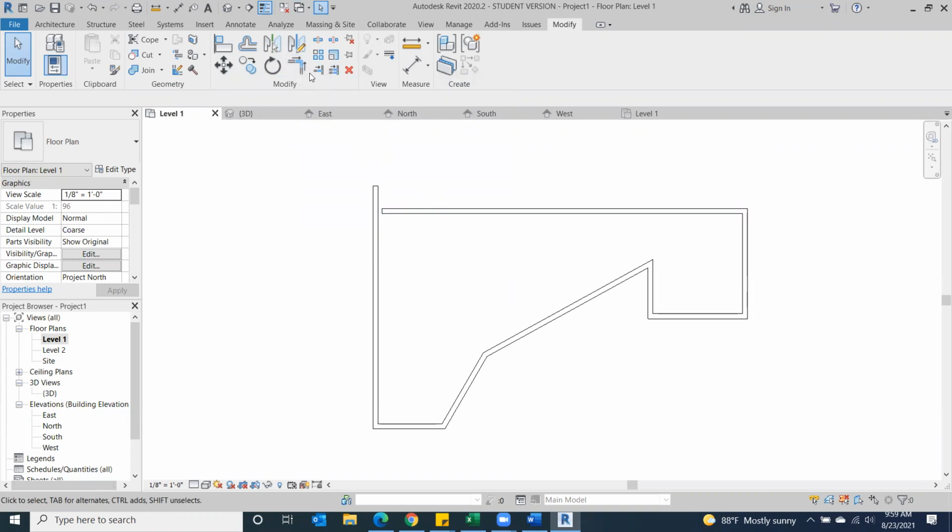So if I wanted to close off this end right here, I can click my Modify corner tool. I'm going to click on the internal angles of what I want. So I want this to end at this point. So I'm going to click on this internal angle. And I click here and I click here, and it's just going to cut that off like that, which is nice. Now, let me go to undo. And say if I wanted to make it connect to this wall and this wall, and wanted to get rid of this one, then I would connect these two angles right here. Those two internal angles, and then it'll cut off that way. It's a nice little corner. So I use that a lot. It's just quick, and anything to make things a little bit faster for you is always good.